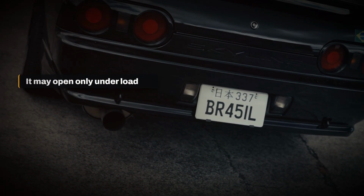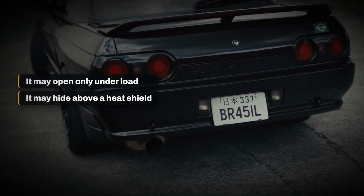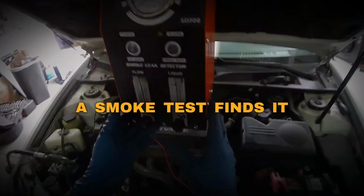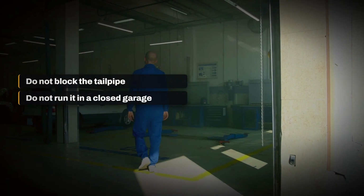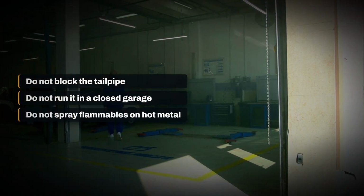Do not assume every leak will be loud. A small leak may open only when the engine moves under load. It may also be hidden above a heat shield or behind another component. A professional smoke test or controlled low-pressure test can locate a leak that is difficult to see. Do not block the tailpipe with your hand. Do not run the engine inside a closed garage. And do not spray flammable chemicals onto a hot exhaust while searching for a leak.